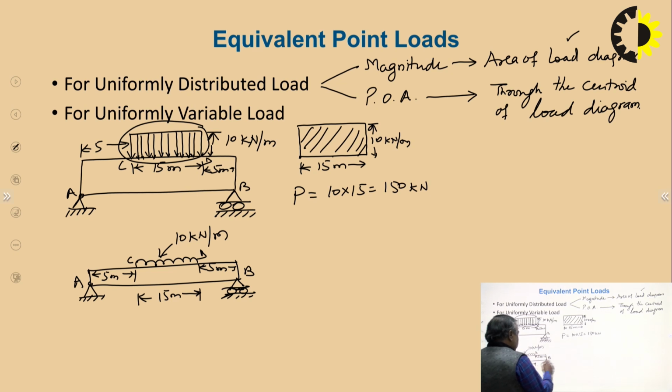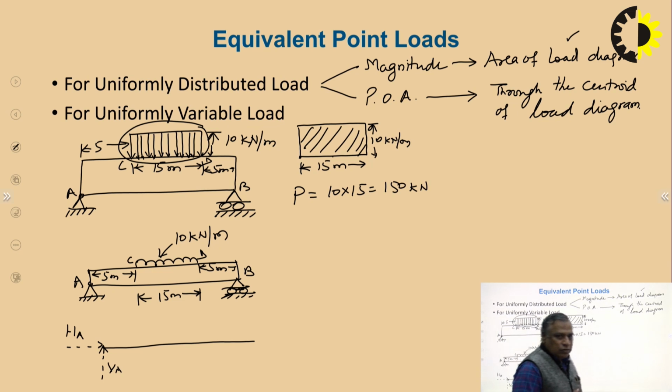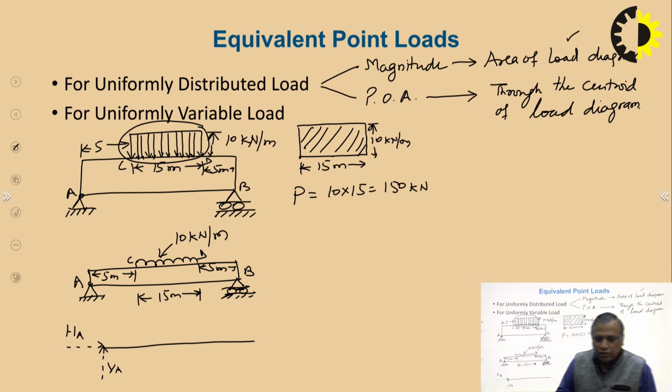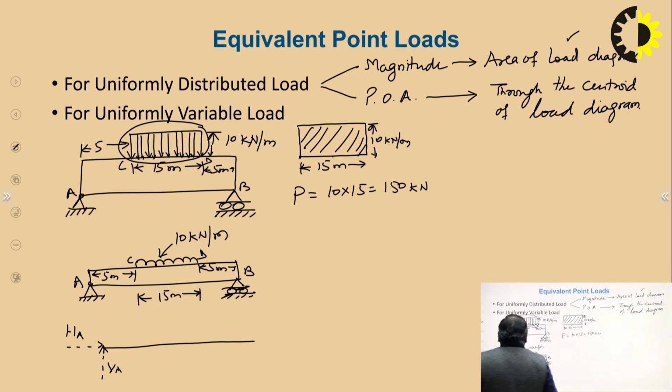So we can draw the free body diagram. This is hinge, that's why dotted. I am repeating again and again why it is dotted, because the direction I will finalize for the hinge after my analysis. If it is positive, then the assumed directions will be perfect. Otherwise, I will change the directions.